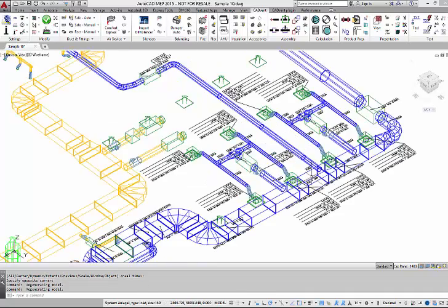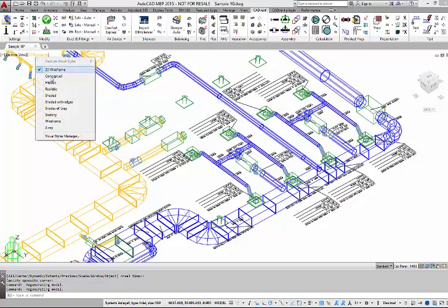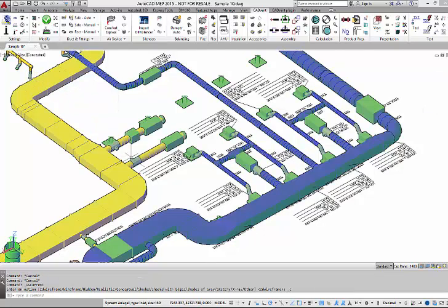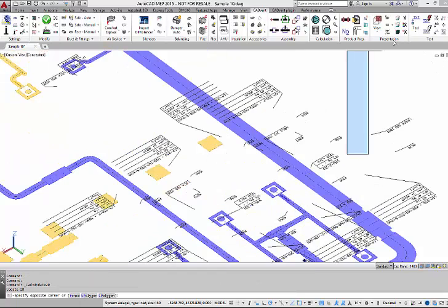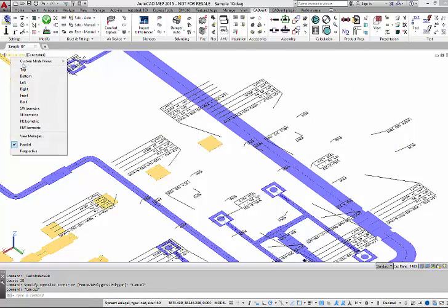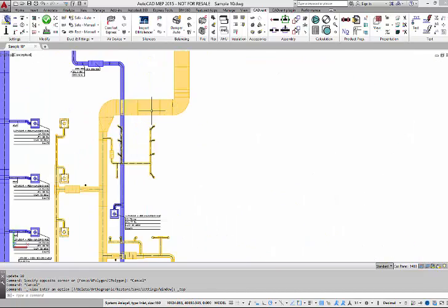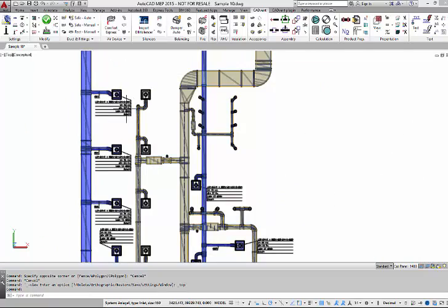You see everything is in 3D. We can shade the system, of course, conceptual shading. You can choose the spiral ducts, but I can also jump into a 2D view. This is also quite flexible. You can use different colors, different layers to show this system. You can fill it, you can shade it, you can leave it open. You can have an external reference to this 2D view. Everything of that is possible. I go back to the top view, so now you can see how it works here.